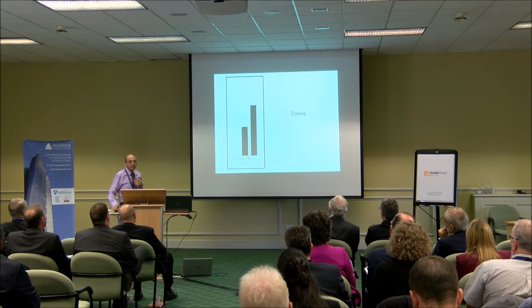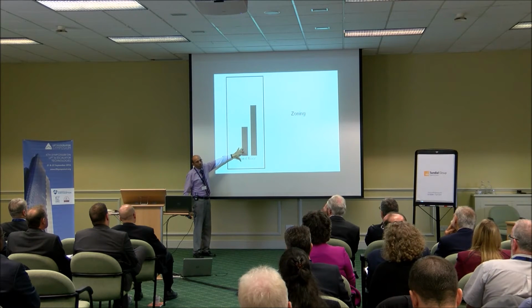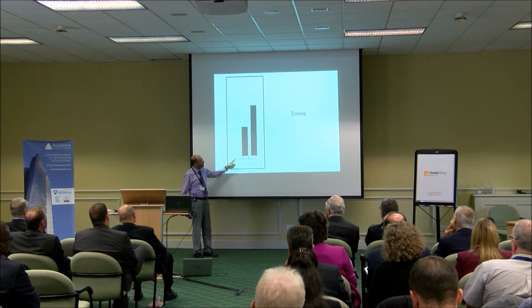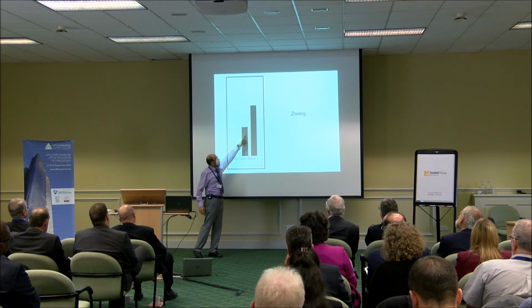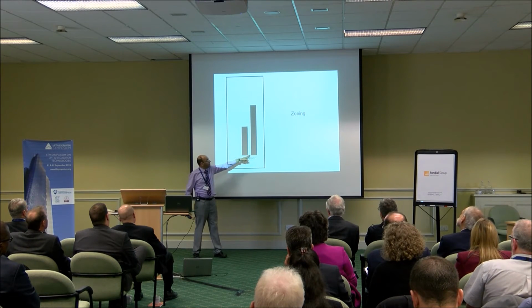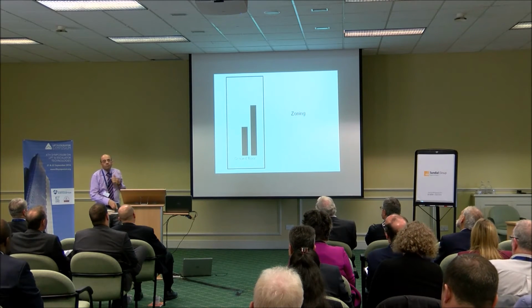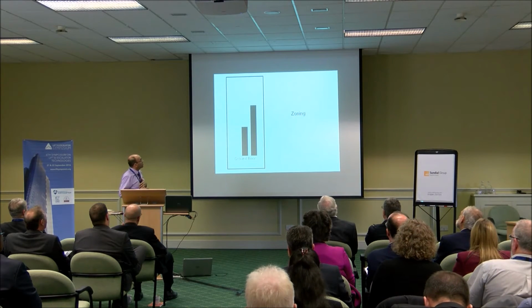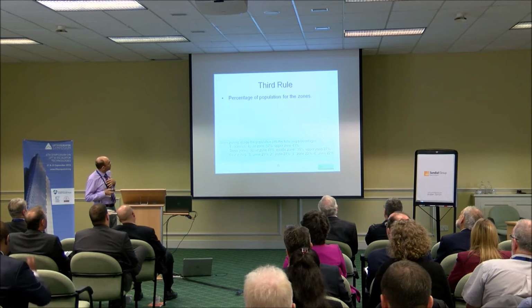And that's an example for zoning. I call this a direct from ground system. That's a luxury we have, but we only have it at low rises or relatively low rises. In a direct from ground system, you have one single journey to get to your destination. So you either take this group and get to a destination, or you express through here and get to a destination, or express through here. At some point, that luxury becomes unsustainable, and you have to have sky lobbies. We need a trigger for that. We need another rule, a rational rule for it. So the third rule is, for example, splitting the zones to equalize the number of elevators.